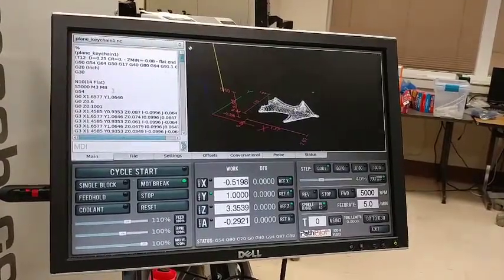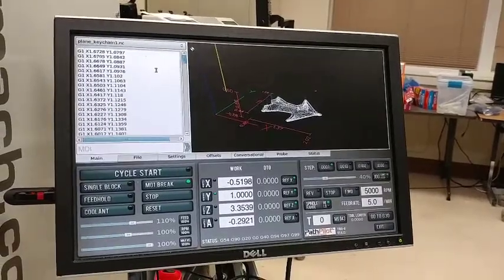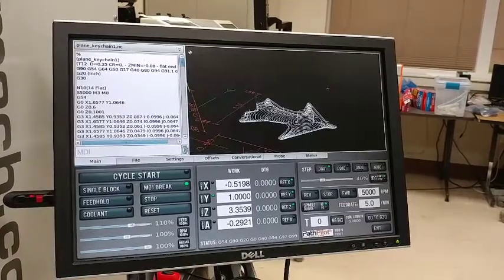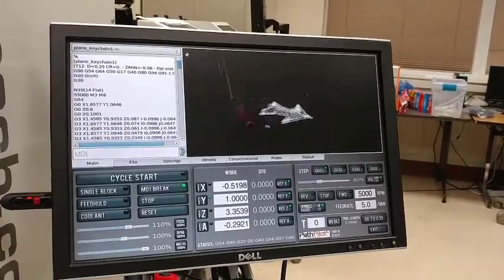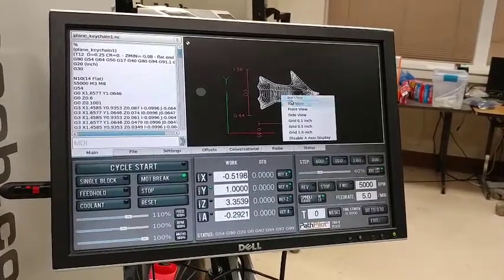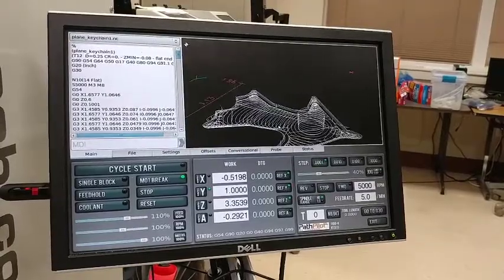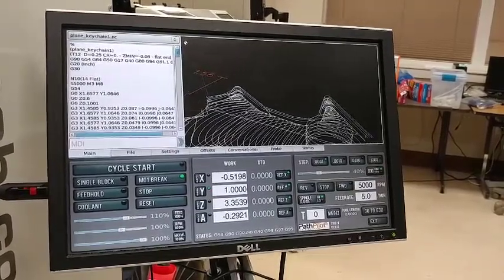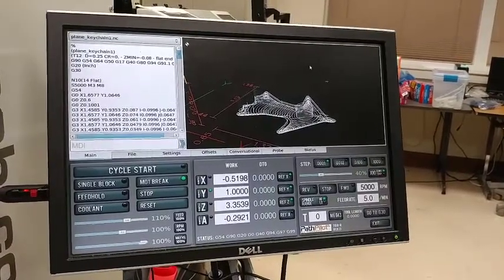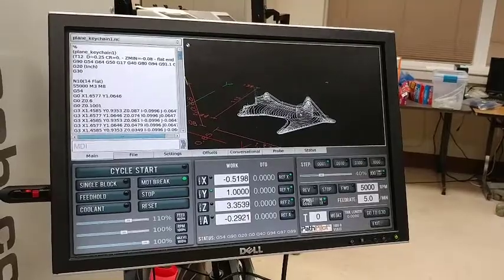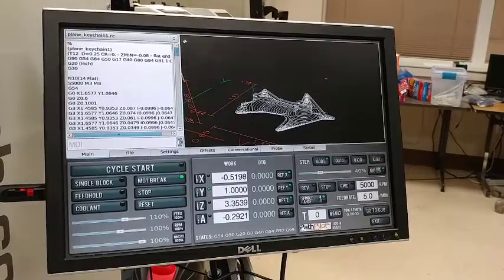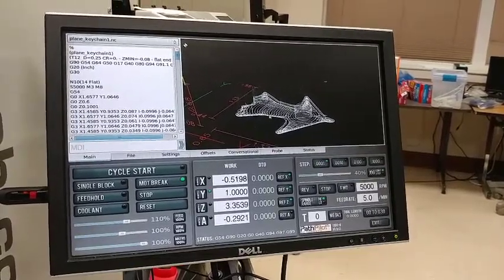It's going to be showing here with all the codes listed on the left, and a preview of the toolpath on the right. And you can actually check all the dimensions from the XY range to the depths of your Z. And if you zoom in, you can see different layers of toolpaths. So for our case, the tool is going to enter from the center. You can see the helical toolpath here, and then it starts cutting around and then going to the corners.